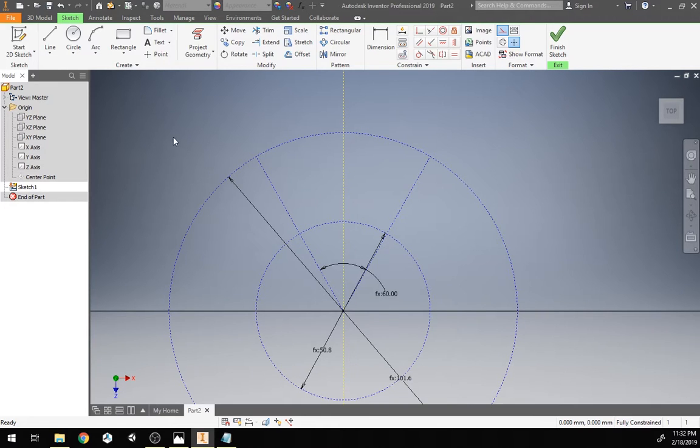And so the first thing that we're going to want to do is let's start off the spike here, and we're going to take off the construction line. And so if we see that green dot right there, that's going to constrain that point, the starting point of our line right there automatically, so we don't have to use a coincident constraint. So let's go up to around here.